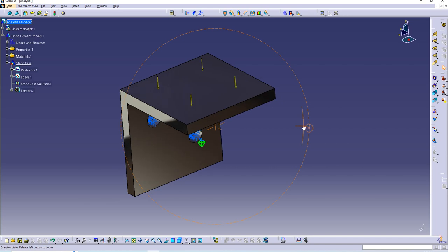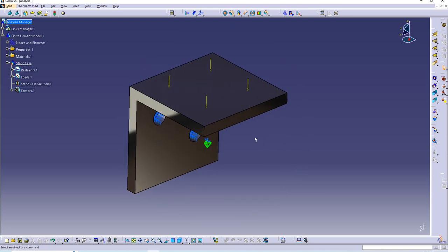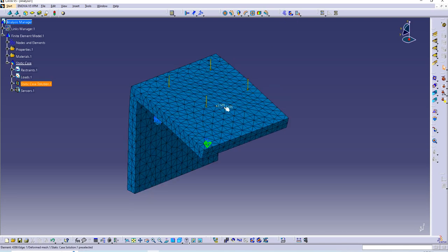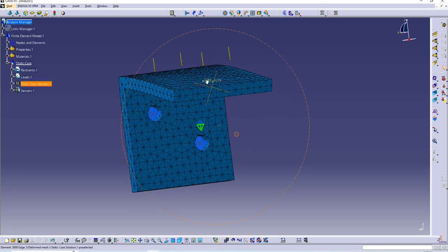Next, what we can see is the post image. What happened just now is the pre-processing, and now this is the post-processing. We have to find this toolbar image. So just click on the three buttons here. We start with deformation. You can see this is how it looks like.